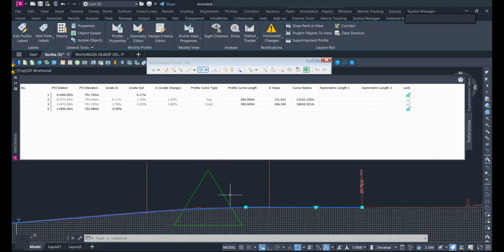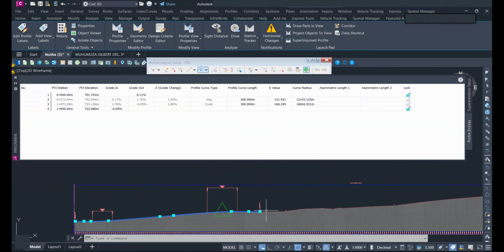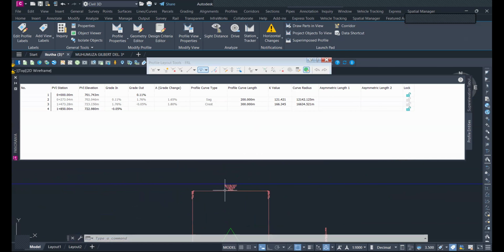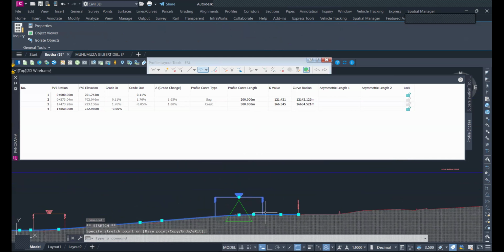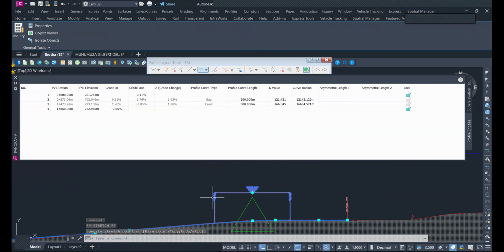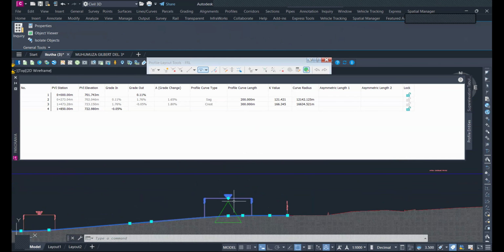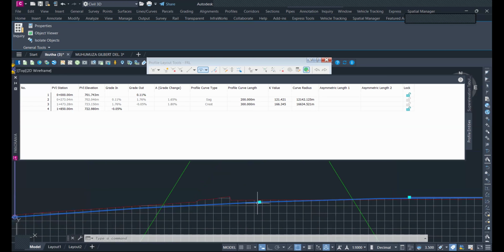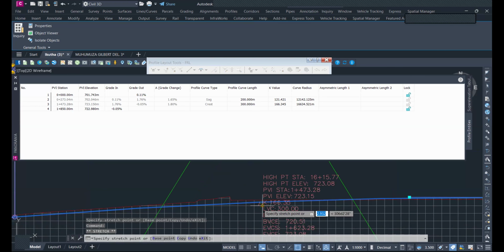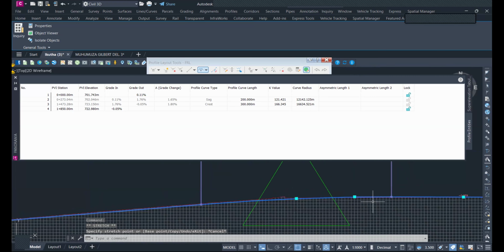Because also, think of it from the perspective of vehicles driving through this section. They need to have a more gentle slope here for the vehicles to be able to drive through the section appropriately. So you need a proper slope here. So that's why we said also this should be a cut. So you just try to make sure that it is not a fill.